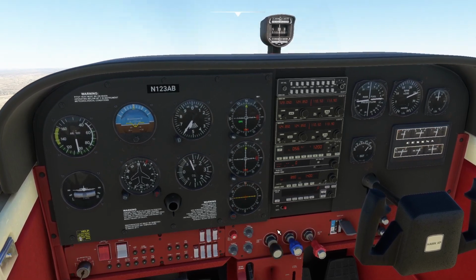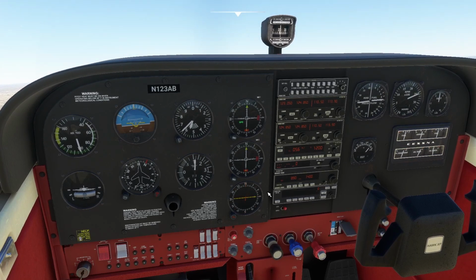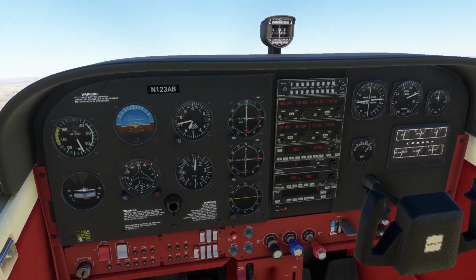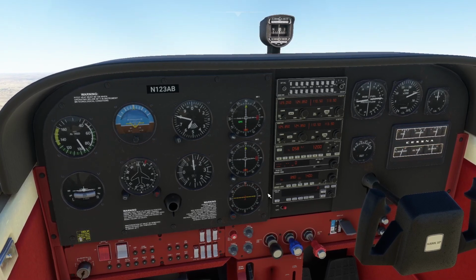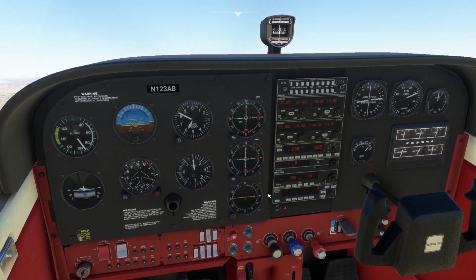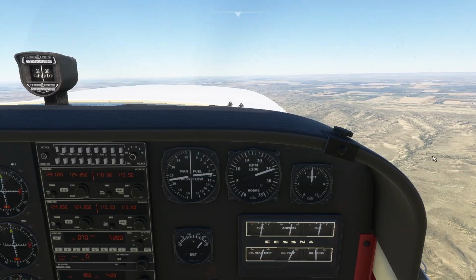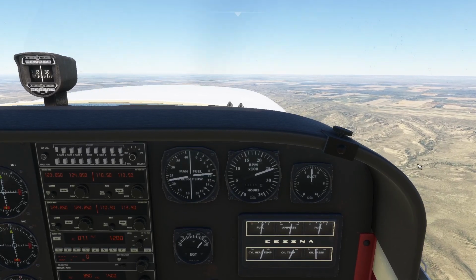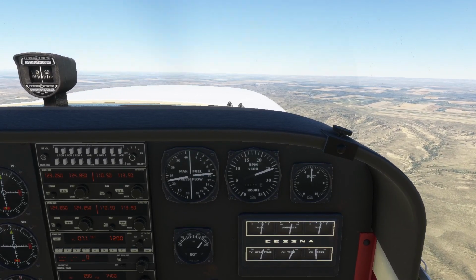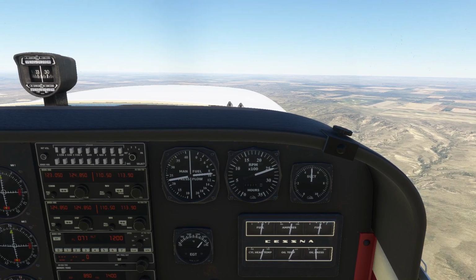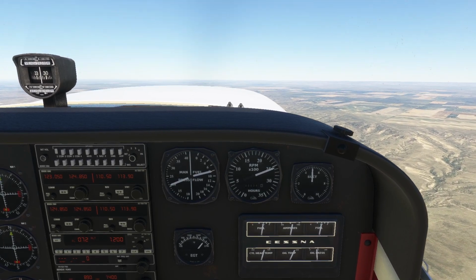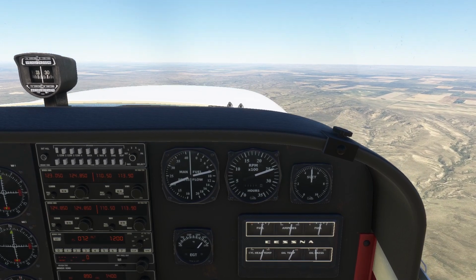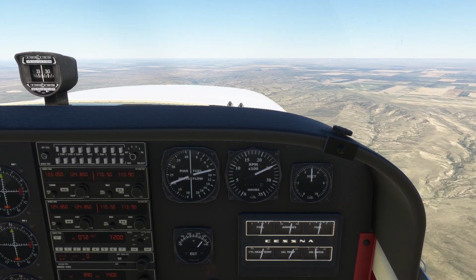As you continue to go up in altitude, you will notice your manifold pressure continues to decrease. This is normal. The manifold pressure gauge also reflects the decrease in air pressure the higher altitudes you go. Following the power management techniques as described will allow you to maintain higher RPMs than your manifold pressure. In most cases, you will fly with the RPMs at a higher value than the manifold pressure.